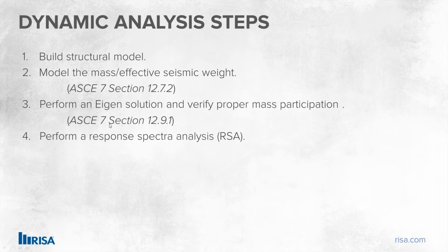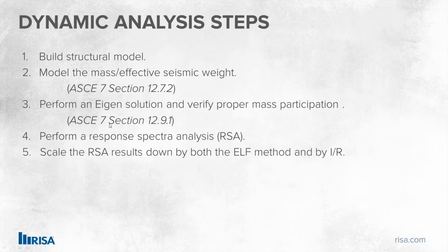Beyond that, we're going to go ahead and perform a response spectra analysis. These steps you can actually do quickly, all at the same time. Number 3 and number 4 are actually going to happen at the same exact time. But this is a separate step: you're going to pick the response spectra analysis that you want to run, typically based on your code or wherever the jurisdiction of your building or structure is. That's going to govern what RSA you want to select. And then you run that, and that will all happen while you're running the dynamic analysis.